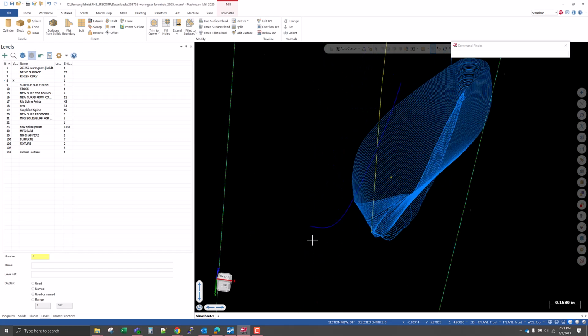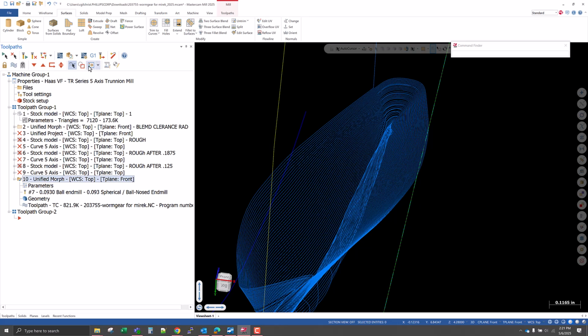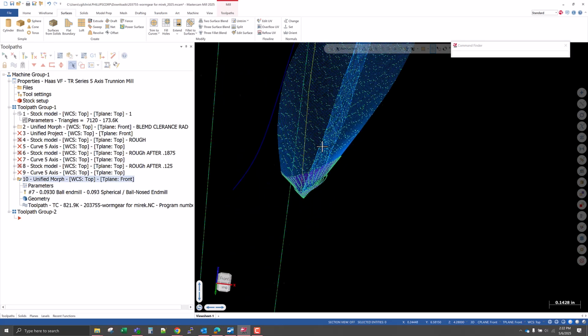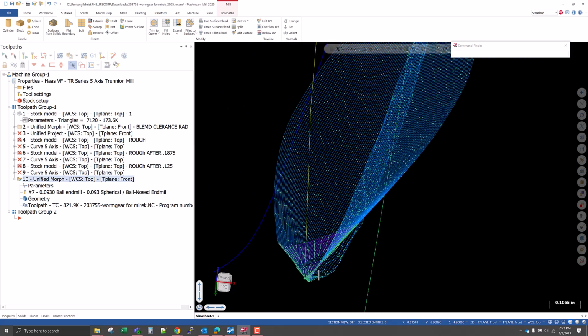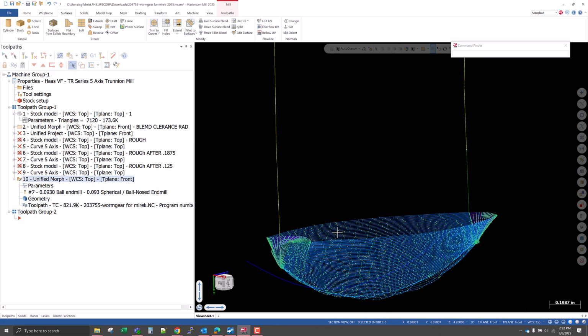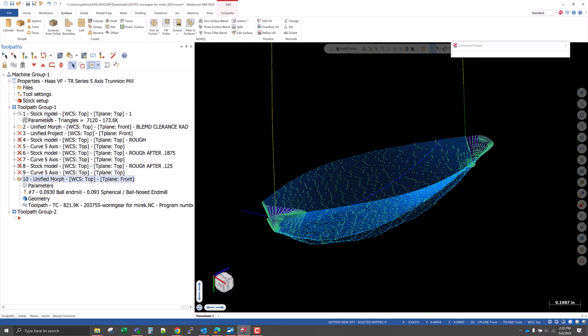Let's look just at the path itself. And if I go under toolpaths and turn on my advanced toolpath button, advanced display, I think is what they call it, I've got my endpoints turned on. And so now you can see the path itself, lots of problems, right? But part of the issue is the shape of the geometry.